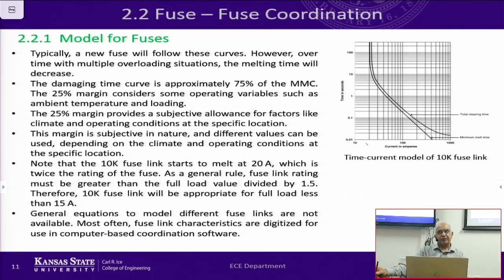Also, in a distribution system, we didn't cover the modeling part of it. One of the challenges is to compute the line parameters, because to calculate the fault currents you need impedance values of transmission or distribution lines. Now, in the transmission system, we assume that the three phases are transposed, but in a distribution system, they are not transposed. So the impedance that you calculate is going to be an approximation, and so the fault currents will also be an approximation. That's why putting in an extra margin sometimes does not hurt.